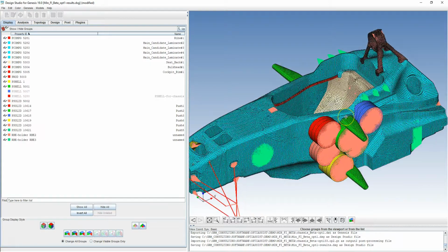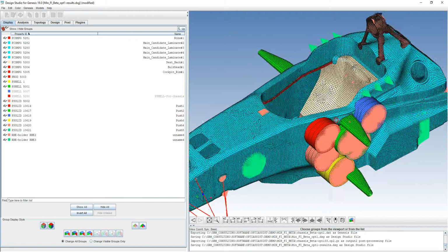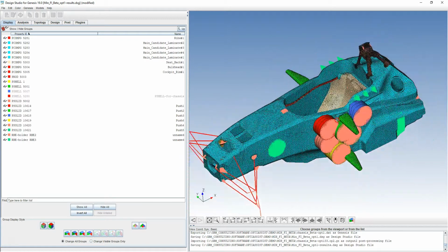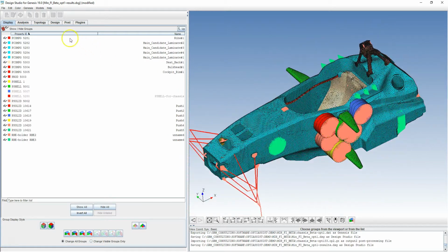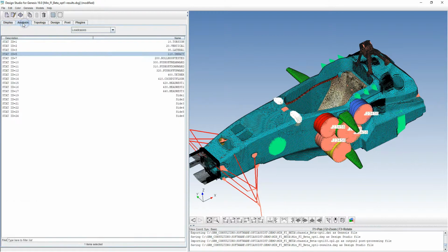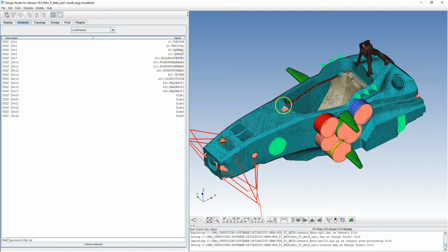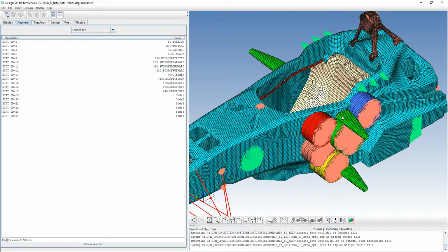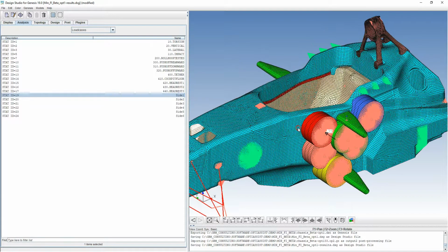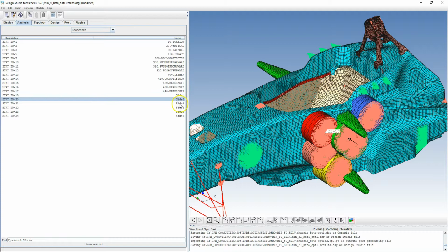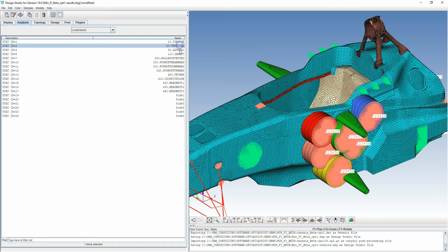So we're doing this on a Formula 1 chassis, and here we're looking at some of the new rules that are actually quite severe for the side. This is an old chassis, but the load cases are fairly up to date. So here we've got a side load applied with pressure pads at 6 different locations, and then we have some stiffness cases and several other strength cases over the chassis.